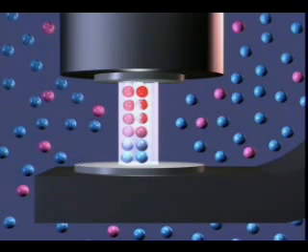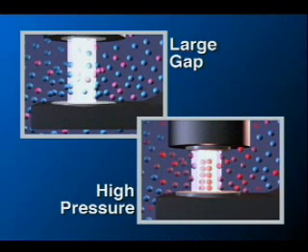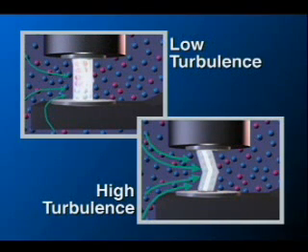The amount of voltage required to fire a spark plug depends on the plug gap, cylinder pressure, and air-fuel turbulence at the time of the coil discharge. Higher cylinder pressure or a wider plug gap places more air-fuel molecules between the electrode and ground strap, increasing the energy required to establish the current flow. Turbulence between the electrode and ground strap requires more energy to prevent the arc from being distorted. 15,000 to 25,000 volts may be required to fire the plug at rated speed and power in a properly tuned ignition system. Higher voltages will be required for a cylinder with worn components.